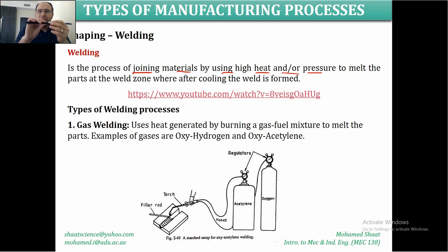So we are going to melt the metal at the weld zone, very small, and you can even observe that it has already melted. Then, with some pressure, we are going to join and make these two parts like a single part. Because if you melt the metal from this part and the metal from the other part, with a slight pressure between them against each other, you are going to mix the two materials together, and upon solidification, once they turn back to the solid state, they are going to be completely one single part.